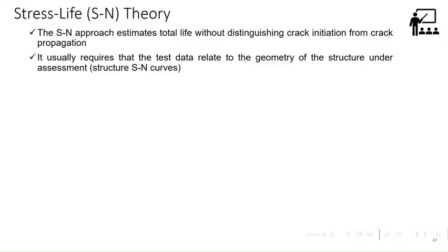Plus, there will always be a requirement to correlate test results with the analytical ones, whether you do hand calculation or FEM analysis using commercial software. But how do you match? There's a difference. You know that the machine component has undergone so many processes. Unless you take care of this correction factor, you cannot come close to the test result. So that is required from both points of view.